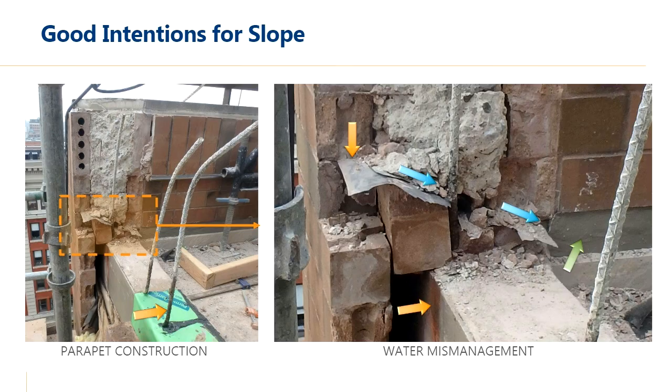So in construction, someone had good intentions for slope, even though we didn't see flashing at that level on those details. You can see the image on the left, a section through here, and that construction we talked about with the concrete filling the brick. On the image on the right, you can see a blow up. We have that PVC flashing that they've put slope in, and they've put slope to drain inwards towards the balcony. But you can see there's no real penetration detailing at the rebar.